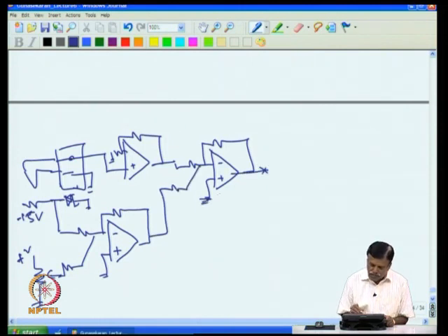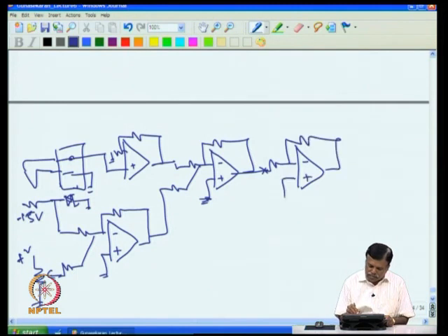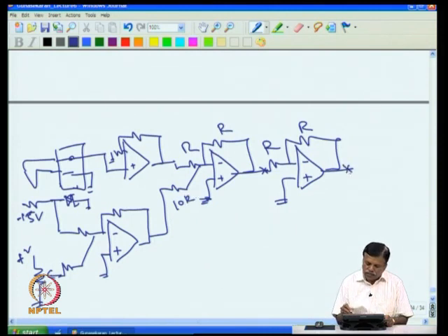Of course, this is going minus side. If we want to make it plus, we can invert it, but I think we will not do that. We can simply invert it to get positive voltage. That would be easier for discussion, but nothing wrong in negative voltage. We can work with negative logic also, but for a beginner it confuses. So I made it such that the gain is here 1, and here you have R and R, we had 10 R. So at this point you will get voltage corresponding to temperature.